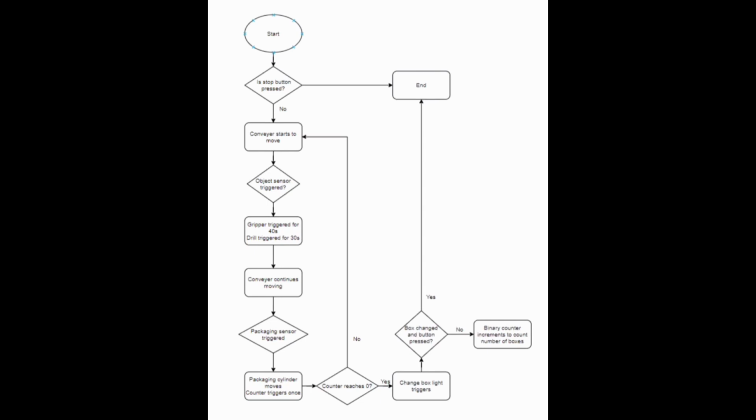When the start button is pressed, yes. The stop button is no. The conveyor will move. When the object sensor trigger is yes, the gripper triggers for 40 seconds and the drill triggers for 30 seconds at the same time.